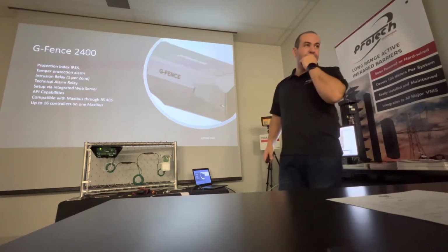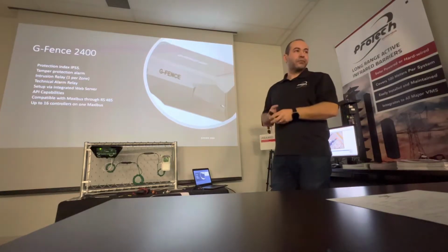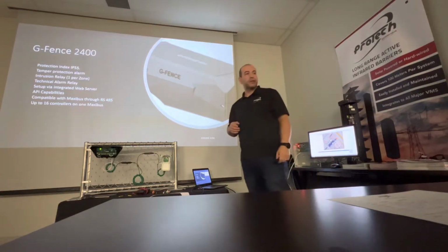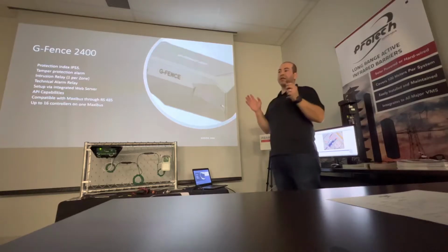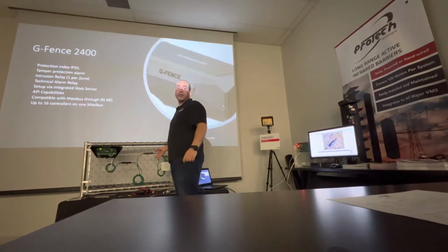Yeah, exactly. So you mean when someone cuts the cable? Yeah, the nearest sensor should by right, it should be a trouble on that sensor. Exactly. And by right, it should cause a trouble on that particular zone if it's zoned in. Exactly. And that will be identified in the software. Yes. So let's say you have a problem with sensor number 12 on zone number 2.